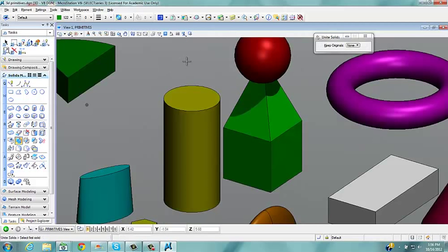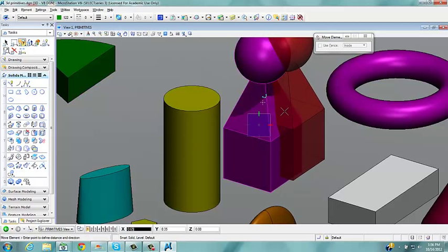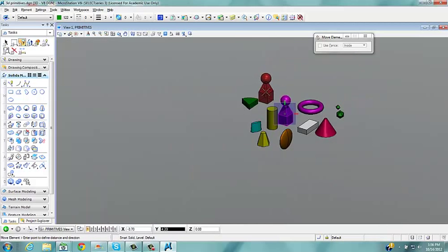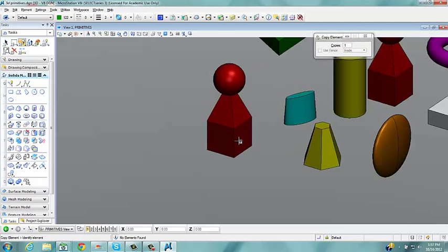And now we'll do the Boolean operation, say find the union of this and this. And now when we go to move this object, it all goes at once. Let's just make a copy of that particular shape, move it over here, and see what else we can do with this. If I knew this is like 2 inches by 2 inches by 2 inches, which is what I drew it at, we can put a fillet on the edges. Fillet is just a rounding of the edge.